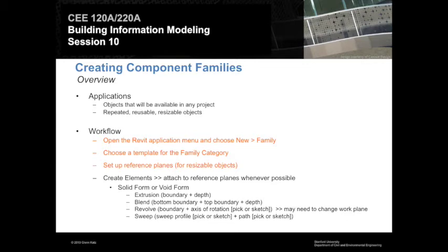And the basic workflow is so similar. We're going to get to this point where it's really just exactly the same as creating an in-place thing. It's creating a solid or a void, extruding it, blending it, revolving it, or sweeping it. It's really the same at that level. The difference is really just at the front part.